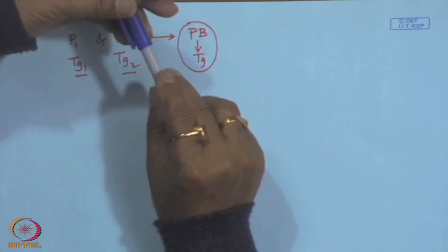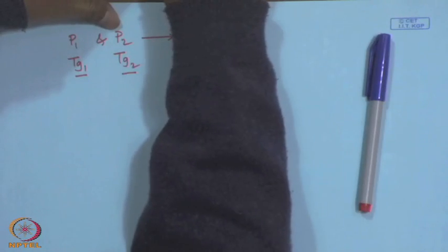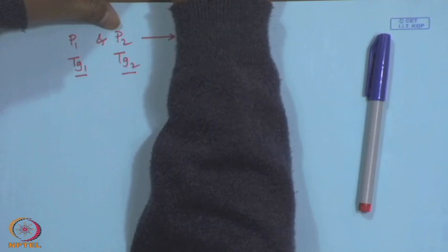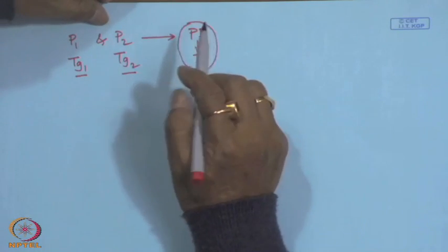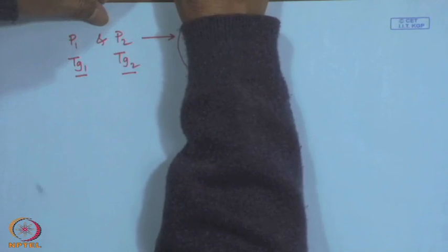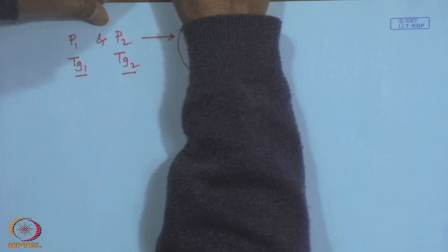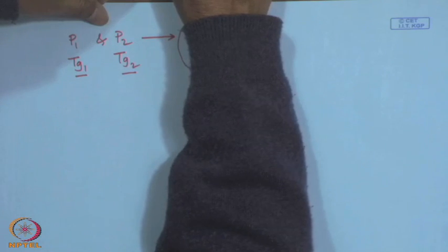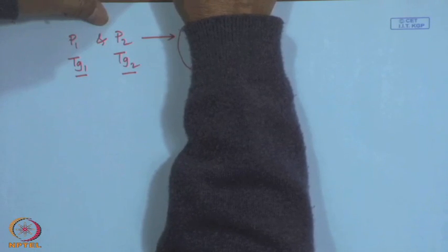So, here the single Tg increases with increasing polyether content, since the Tg2 of the polyether, polyphenylene oxide, is higher than the Tg1 of polystyrene. So, on increasing the polyether component in the blend, the final Tg of the resultant polymer blend increases with the increase of polyether content.